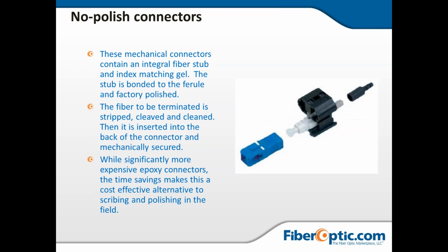The fiber to be terminated is stripped, cleaved, and cleaned. Then it's inserted into the back of the connector and mechanically secured. While significantly more expensive than epoxy connectors, the time savings make this a cost-effective alternative to scribing and polishing in the field.